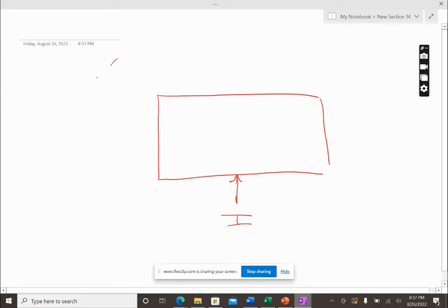And ideally we wanted to measure the temperature at the surface of the slab, and we also measured at 2 inches below, 4 inches, and 6 inches. So in this case, our delta Z was 6 inches. Because to measure thermal conductivity we had to use meters, it's 0.1514 meters.